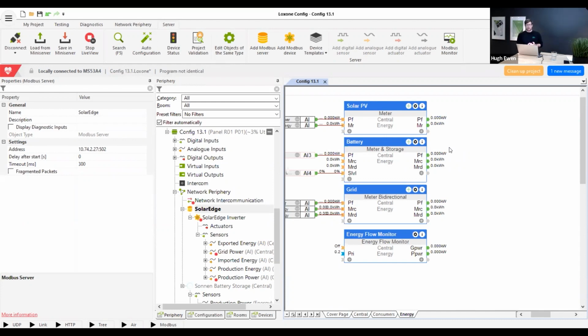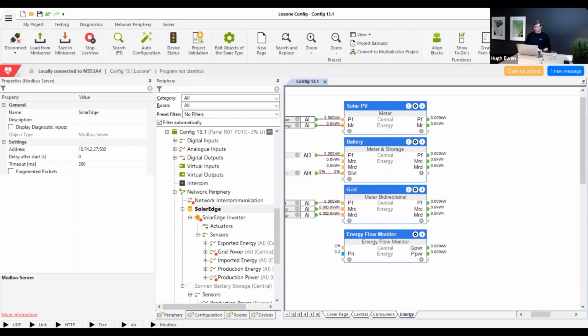If it is a relay, that means it turns on and off. That's the only thing it does. And something that turns on or off is either 0 or 100%. So if, for instance, it is an immersion heater, and it's a 3 kilowatt immersion heater, when that relay is off, it draws nothing. When that relay is on, it draws 3 kilowatts. So instead of us putting expensive hardware inside the relay extension just to tell us something that we could get by just merely counting, we actually decided that the 7th meter block that we would add